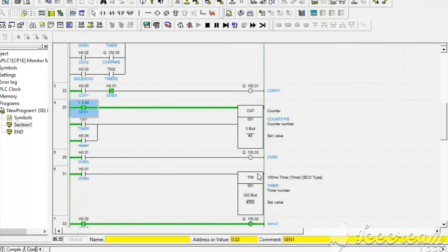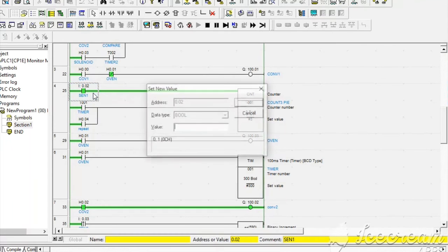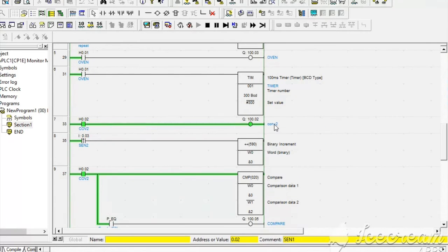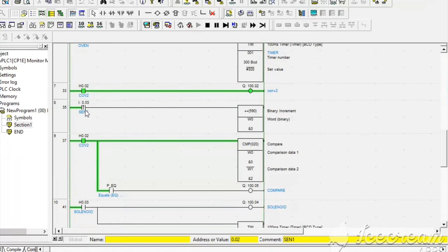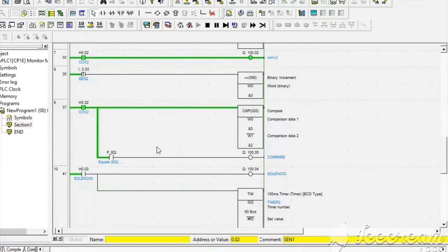Okay, what will happen is now the conveyor is still off. This sensor, we will remove it from the counter here. It will be 0 again, because this one, conveyor one, is off. Here we go to conveyor number 2, which is located after the oven, and will be energized and start moving and running. After that, we will see here the math function compare, which will compare W0 and W1. In this case, the initial values are still here, meaning W0 is 0 and W1 is 3, or 2 for this example, for the simulation's sake.